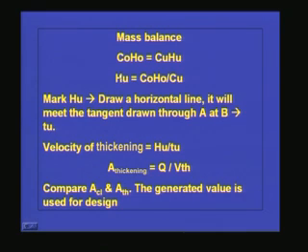So, how can we find out HU? HU is equal to C0 H0 by Cu, because at any time C0 H0 is equal to Cu HU. We are not removing anything from the system, so the total sludge mass will remain constant. And how can we get Cu? Cu will be your design sludge concentration. So, from this we can find out the HU value. HU is nothing but C0 H0 by Cu, where Cu is the desired sludge concentration we need from the secondary clarifier.